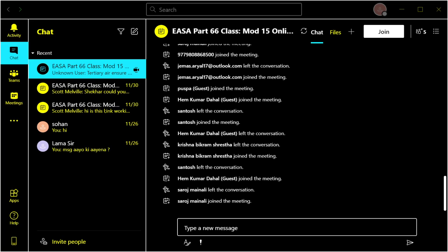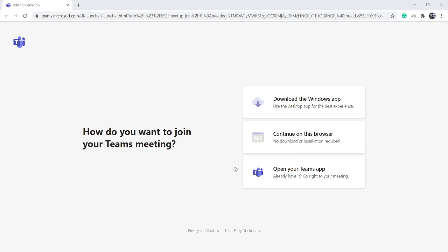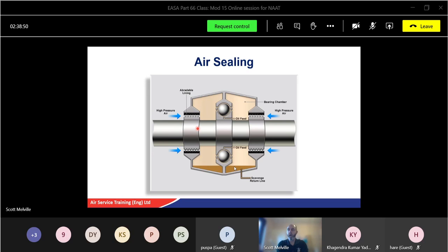As you can see here, we'll get a small jet of oil going into the bearing, surrounds the bearing, and once it's done its job, it will return back to the scavenge line. Now, that's all very well. The oil comes in and it goes out. Now, if there's nothing to stop it going out the shaft, then it would just disappear at the shaft, front of the compressor, back of the turbine, and make a lot of mess and obviously potentially on fire as well.